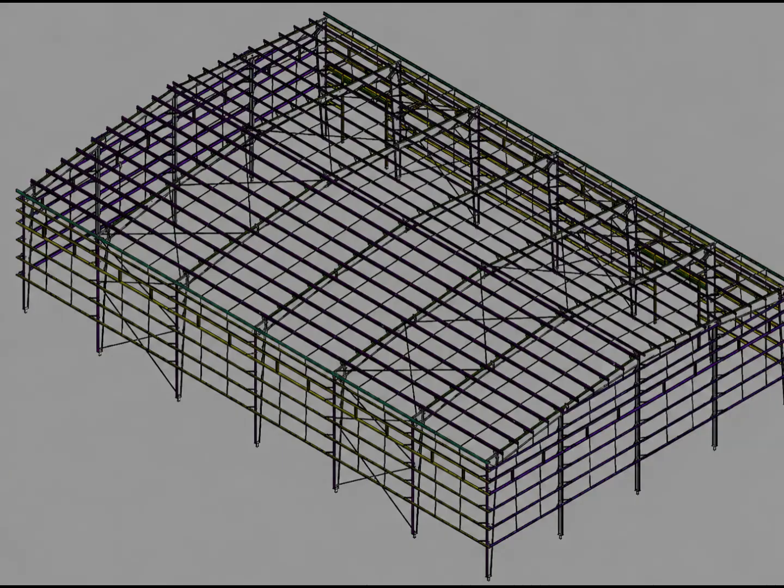Now remember what we saw in the roof framing plan. The drawing showed the locations of the sag rods in relation to the roof purlins. When we move from that 2D plan into this 3D model, we are essentially transferring the same information into three-dimensional space. The important point is that we should not randomly search for a thin rod in the model. Instead, we should start from the known location shown in the framing drawing and then follow that location into the 3D model. This gives us a very useful practical method.